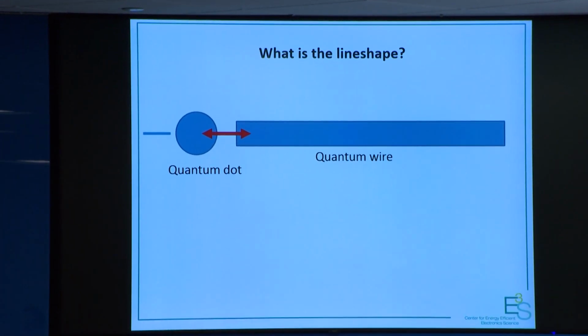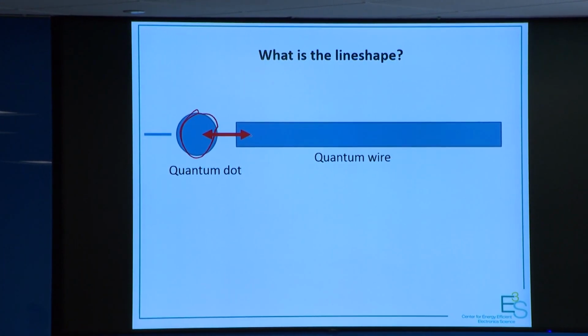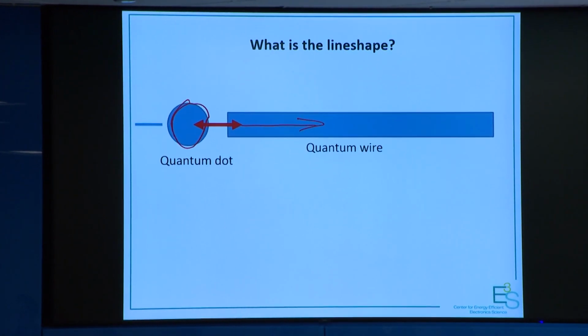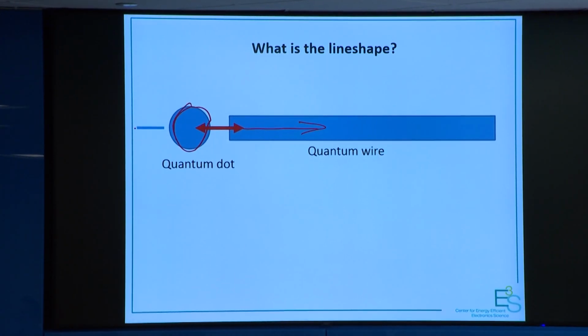ask what happens. Now you're interacting. Now the spectral line is interacting with a contact because I didn't show it, but I think I'll show it. Here it is. You have your quantum dot. It has to be connected to a wire. So you have many things that could broaden. So you have a sharp level. And you say, well, there are a lot of things, there's disturbances all over. But the biggest disturbance is you've got to connect a wire to it. So the electron cannot stay on the quantum dot very long. It has to go into the wire and be collected. And so that's going to contribute to the line width. But all the other things are also going to contribute to the line width. So let's try to figure out how we could possibly get the line width sharp enough to make a tunnel FET successful.